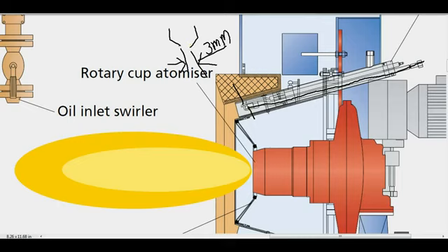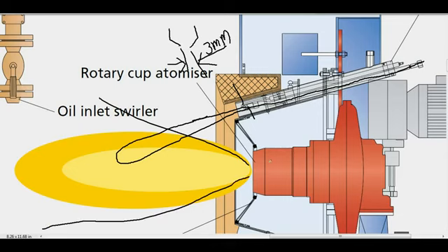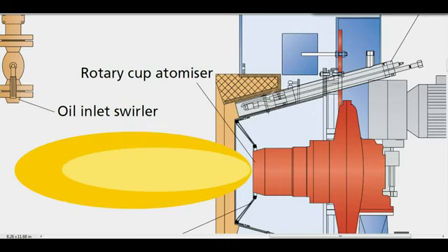Only when it is properly adjusted, the diesel oil, when it comes out, catches flame and then interferes here with the main fuel mist. As the flame of the pilot burner extends in this area, as we know, there is a huge mist which is coming out of the main burner. It catches a flame, and once the flame cell or the flame sensor detects the flame, the pilot fuel is cut off. Once the pilot fuel is cut off, the main flame catches and then it keeps firing.